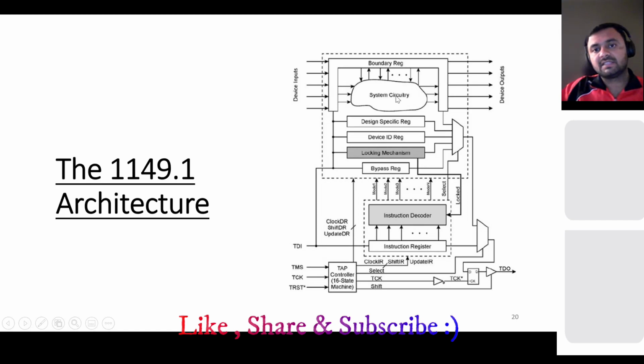You can see here your chip is placed in the system circuitry, and then you have the boundary registers here. It's just like a wrapper. And then you have the functional input, that is device input, and then your test input. So there is a mechanism to test it. You put your data in from this TDI, shift it through the boundary scan cells, and then shift out to get the response.